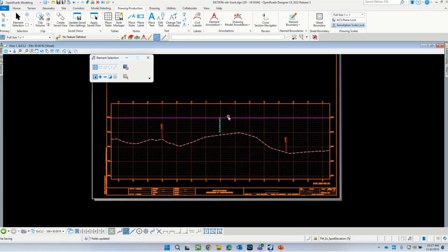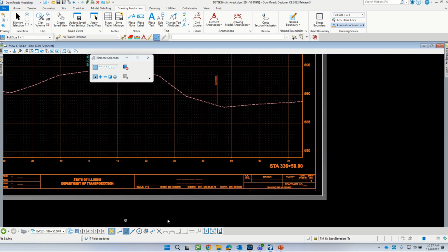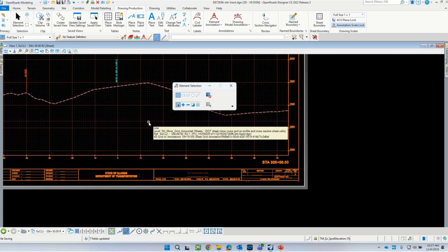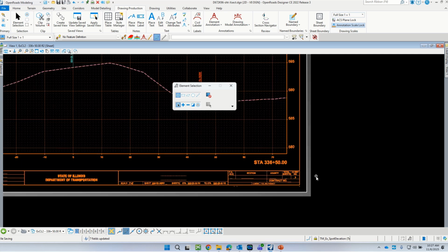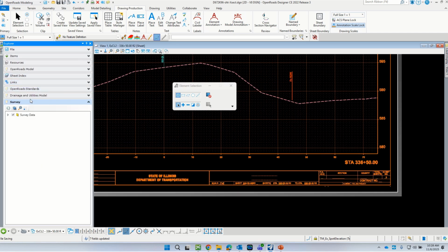And then if we would like to go ahead and populate all this information here, we can do so in the sheet title block. And again, that's because, well, actually we can't. That's only if this was in the sheet index. I may actually typically wait for that until I've added, say, cross sections at entrances. I get it just right, and then I might just reprocess the sheets, that sort of thing. But while we're here, let me just do a little refresher on how we go about doing that. We'll probably remove the sheets from the index and re-add them later, but this is a good learning experience here.